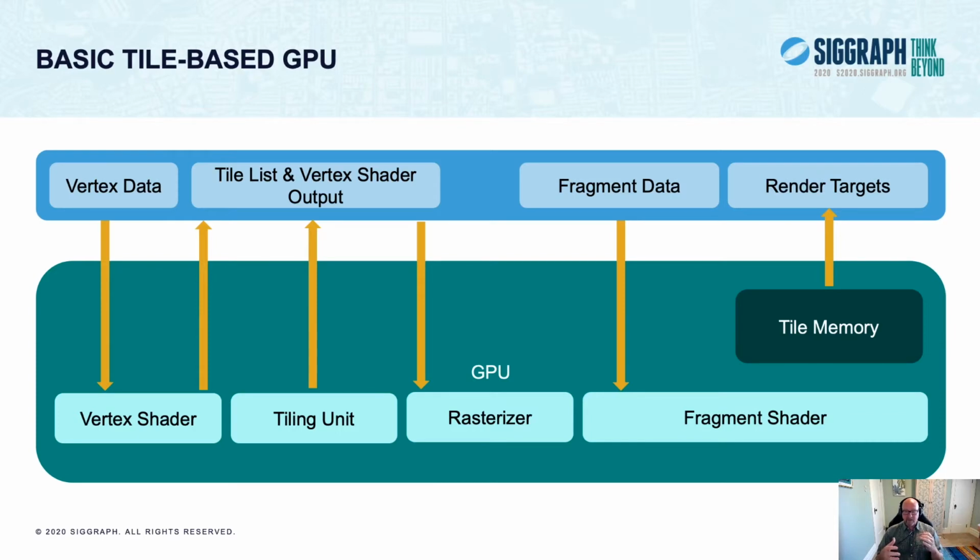And because we know a lot about the geometry, as I say, from this early binning process, there are a series of early depth tests that can be done prior to rasterization, and those enable certain optimizations at the hardware level. So, for example, there's one called forward pixel kill, which can remove a fragment that's already made it down into the queue. But because the realization comes that it's going to be overwritten, it just gets yanked out of the queue, so it never gets processed any further than that.